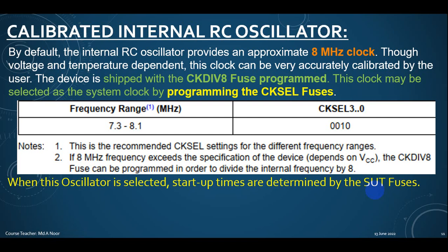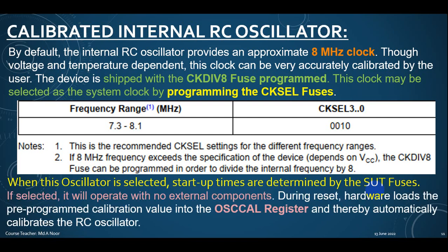If selected, it will operate with no external components. During reset, hardware loads the pre-programmed calibration value into the OSCCAL register and thereby automatically calibrates the RC oscillator.